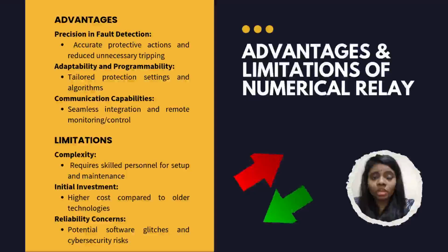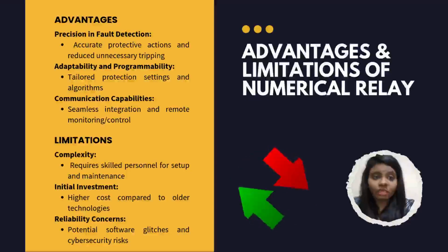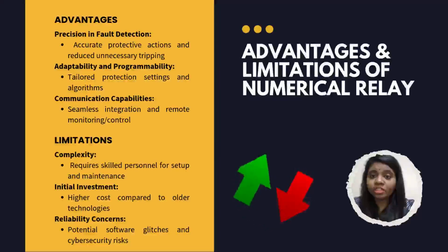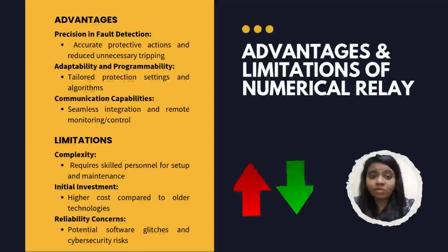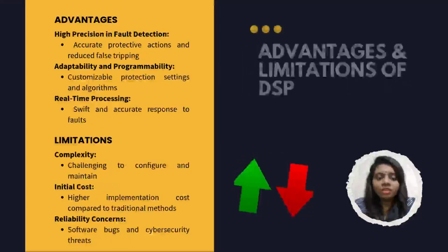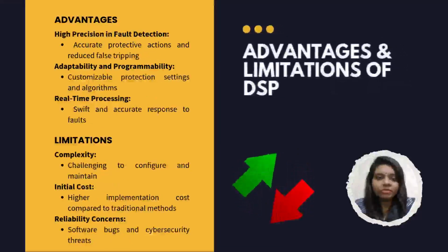However, numerical relays also have limitations. Their complexity requires skilled personnel for setup and maintenance. They involve a high initial investment compared to older technology. Potential software glitches and cyber security risks can affect reliability, and integrating relays from different manufacturers can cause compromise. Advantages and disadvantages of DSP.